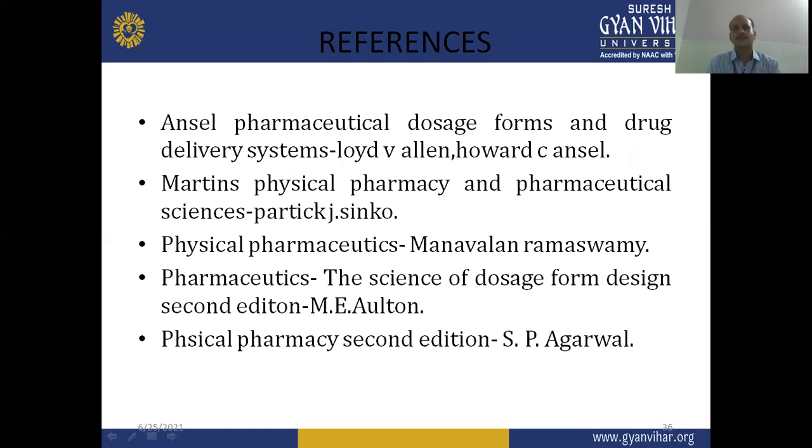So today's discussion, when we summarize it, was based on the different types of liquid behaviors. Based on Newton's law of flow, we can classify the flow behavior of liquids into non-Newtonian as well as Newtonian types of liquids. Non-Newtonian liquids can be further classified into three classes: plastic flow, pseudoplastic flow, and dilatant flow.